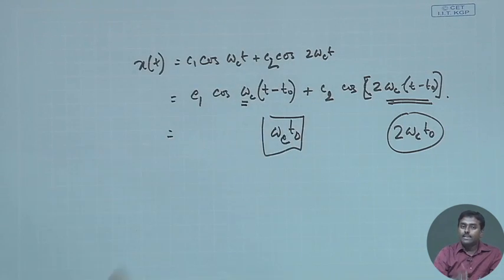That is if I pass it through a delay element, whereas when we pass it through a Hilbert transform, both of them will get an equivalent phase shift, all pi by 2. Immediately, they will have equal phase shift, but the delay will be different for different frequency elements. So if a signal is composed of multiple frequency elements, they will be separately delayed.